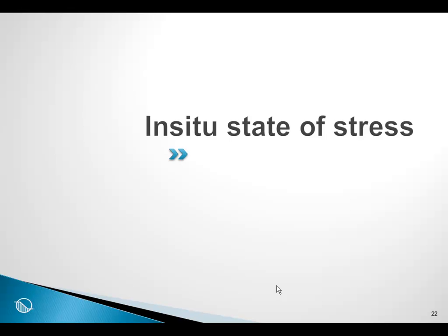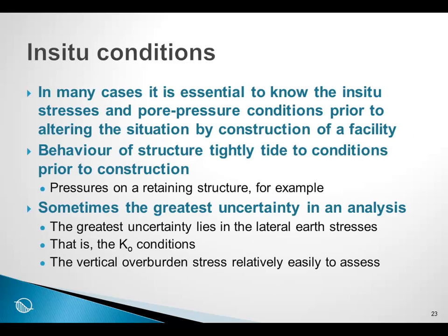In situ state of stress. In many cases, it is essential to know the in situ stresses and pore pressure conditions prior to altering the situation by the construction of a facility. The response of the soil and the behavior of the structure is tightly tied to the conditions prior to construction. For example,